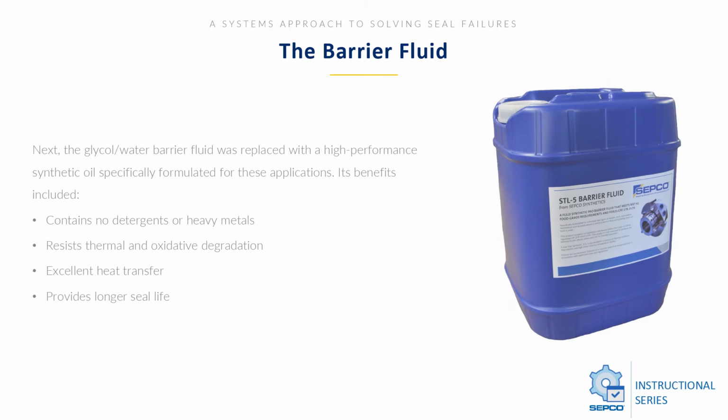Next, we wanted to look at the barrier fluid. They were using glycol and water. They were using the wrong glycol, and that glycol and water mix was not sufficient to handle the heat that was generated between the process and the mechanical seal generated heat.